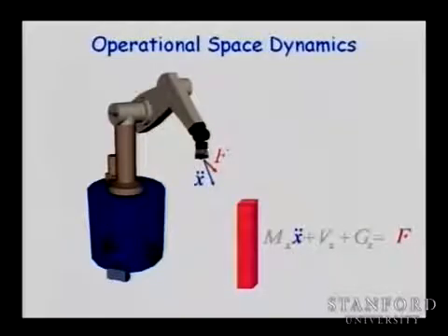And if we obtain this model, which is simply a relationship between forces and acceleration, velocities and positions, at a different configuration, you have different properties. Once you have this model, you can do the same thing we did with controlling the robot in joint space, by decoupling, making an estimate of this, and making an f star or f prime. Now we select an f that is proportional to the mass, the estimate of the mass matrix, with compensations of centrifugal, Coriolis, and gravity forces. And then you can control it.